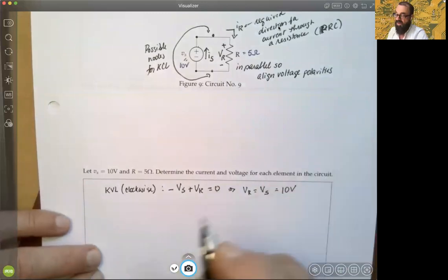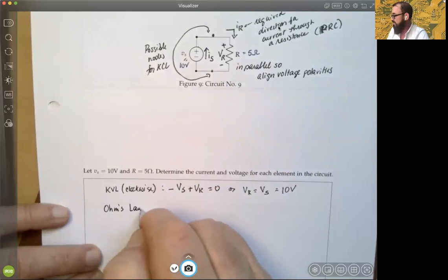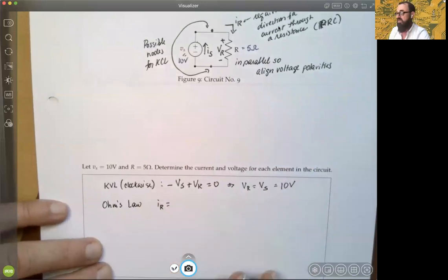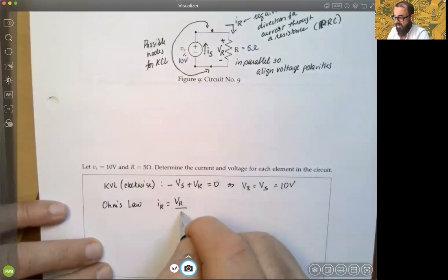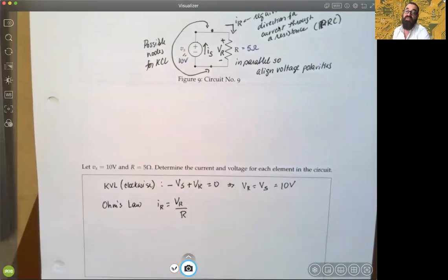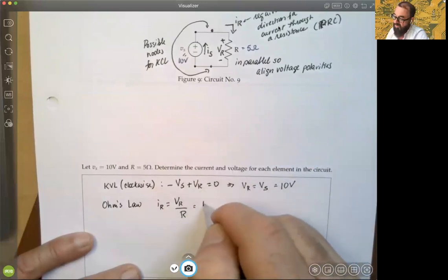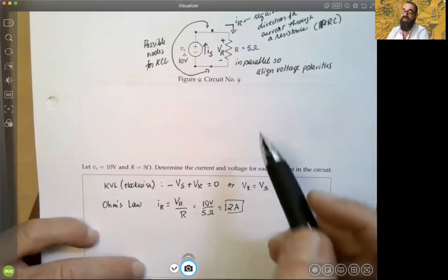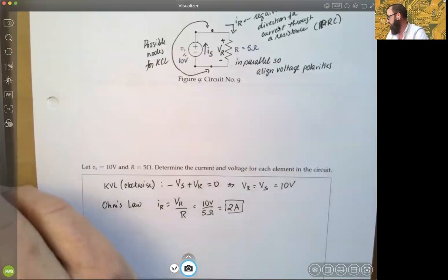All right, so via Ohm's law, since we're talking about currents, we know that the current through that resistance must be the ratio of the voltage to the resistance R, right? Again, that's another way of looking at Ohm's law. In this case, it's 10 volts divided by the 5 ohms, and that's just going to be 2 amps. So we know that there are 2 amps flowing through that 5 ohm resistance, okay?